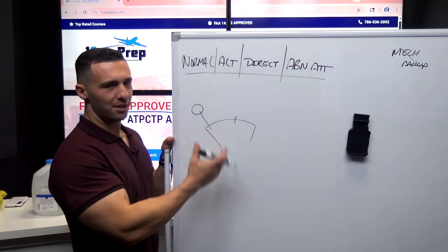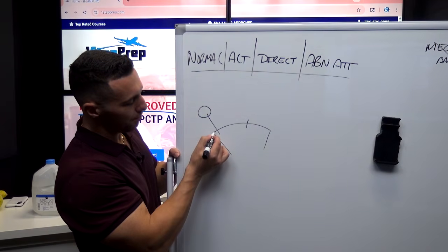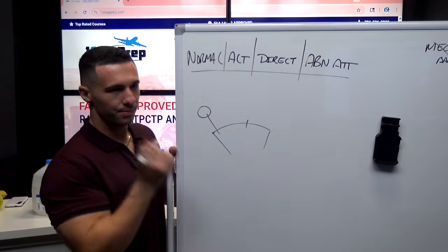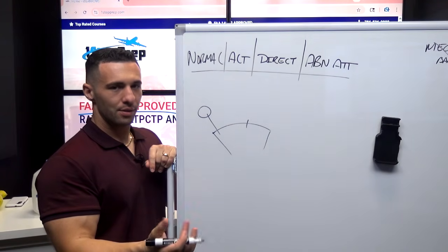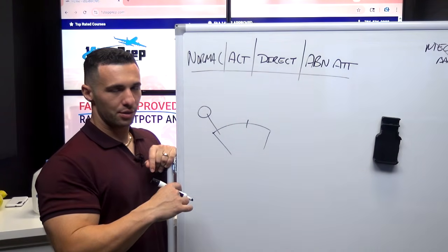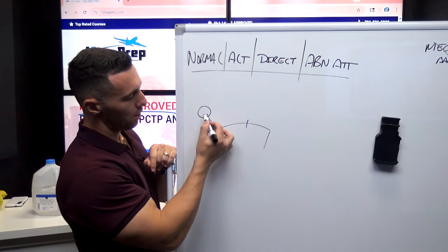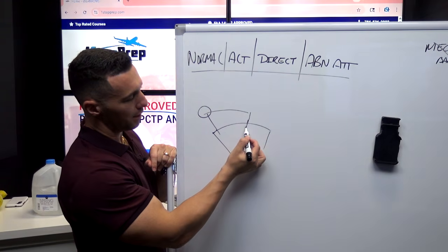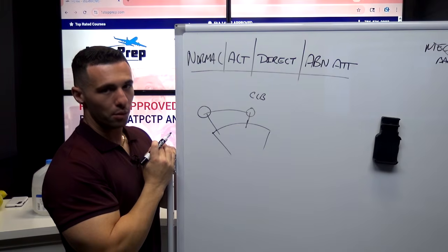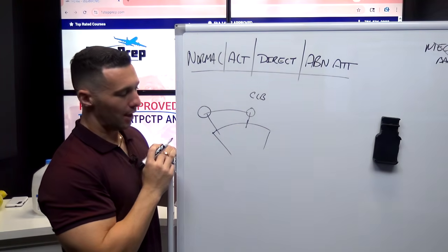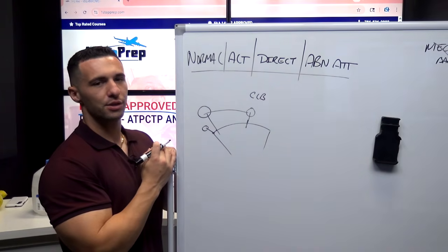So imagine for a moment that this is your thrust levers here, your throttle quadrant, and this point is idle. Your auto thrust active range, with 2 engines, is just above idle up to and including climb. So, in other words, if I bring the thrust levers here to idle, I'm out of the active range.